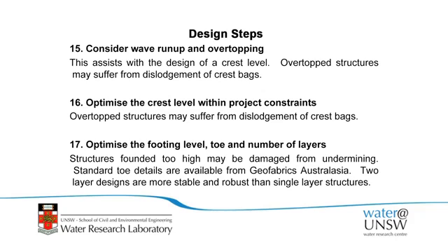If it is an overtop structure, I've got a photo of it, you'll see the most common damage mechanism is the crest bags are damaged. So you need to think about some clever ways of designing the crest. So when you know what the run-up level is, optimise the crest within the project constraints. Overtop structures may suffer a different damage mechanism to structures which are not overtopped, but it's just a real-world reality. Sometimes you need to allow them to overtop.